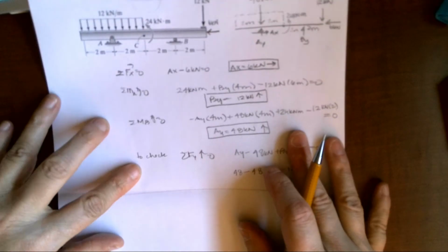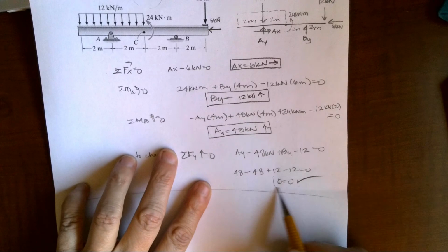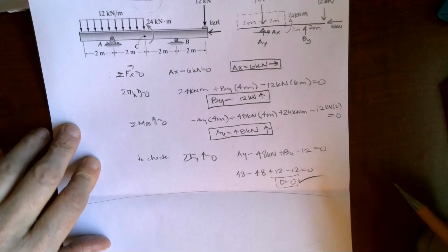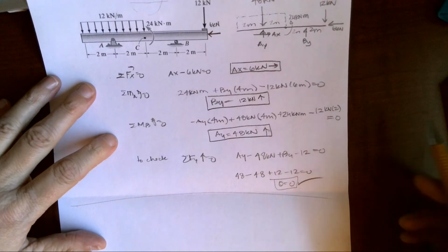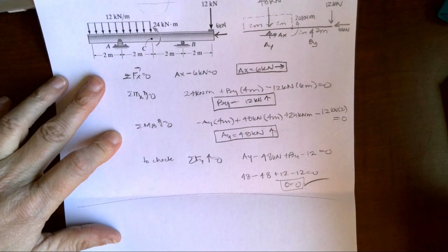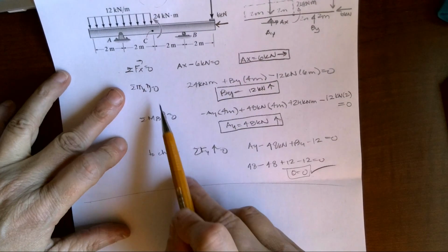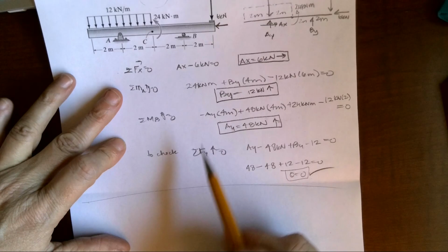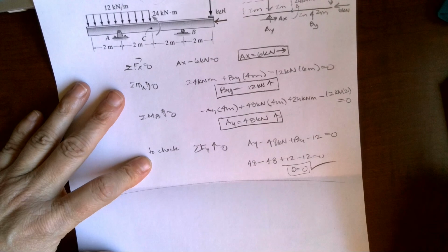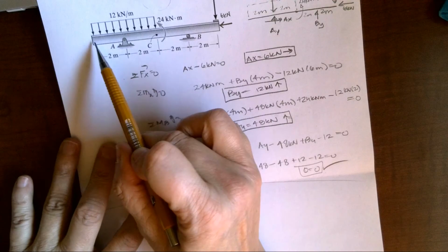I know I say this all the time, you should never have a wrong answer in statics because the sum of our forces always equals 0. It doesn't matter where we sum moments. The sum of the moments has to equal 0. So I found my reactions by summing moments about the other respective reaction, and then just checked my forces in the y direction. Okay, so we are going to work this problem looking at both the left and the right.